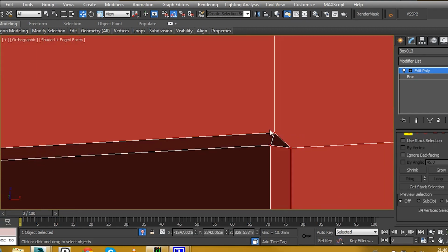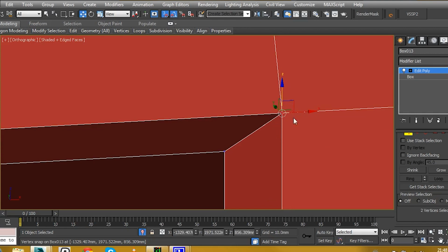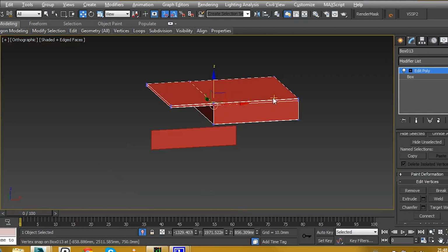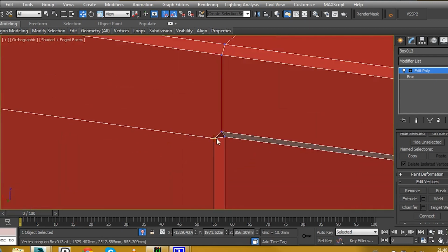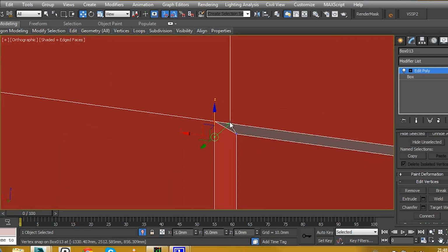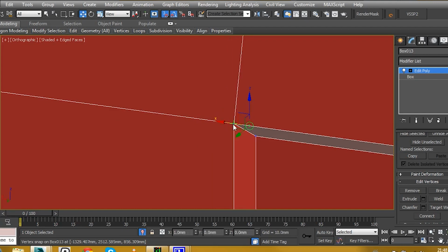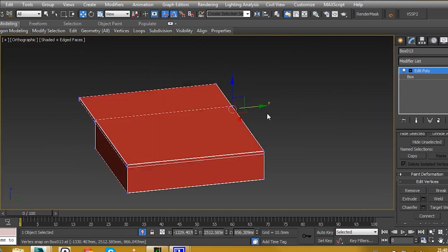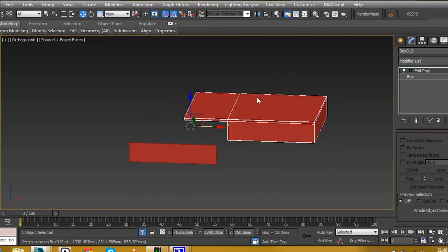If you go to your vertices, we'll just select this one, turn on your 3D snap, and snap it on the x-axis to this point. We'll do the same with this point, on the z-axis to that point. If you highlight over these, there'll be two there, and we'll just weld these together. You can see it's removed one. OK that. I'll show you again round the other side. Just select this vertex here, snap it up to that one there, snap it back along, select the two of them, and weld. This ensures we're only working with quads. Deselect that.